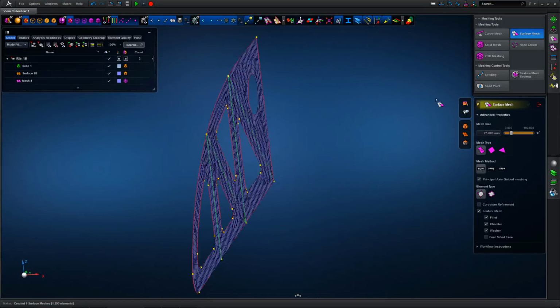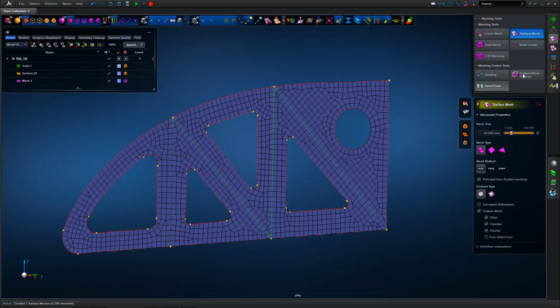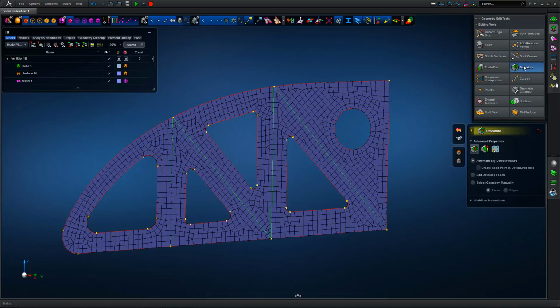So some local edits: remove unnecessary vertices to simplify the structure for resultant meshing, and then we just take a typical 25mm element edge length, mesh using the default mixed tri and quad with auto algorithm turned on, and the mesh is generated very quickly with pretty good definition based on that element edge length.